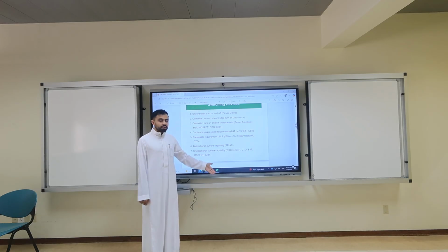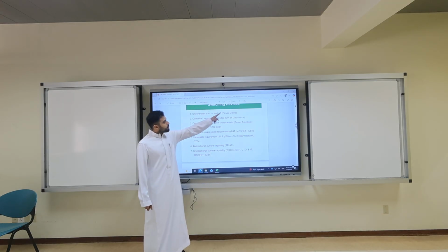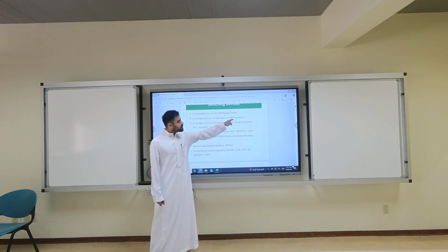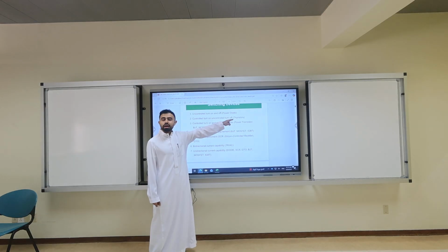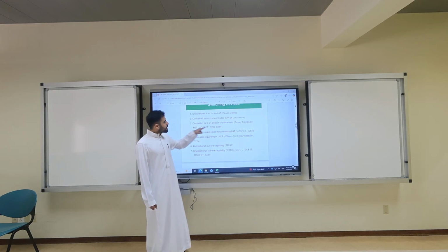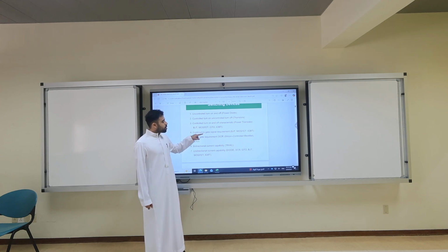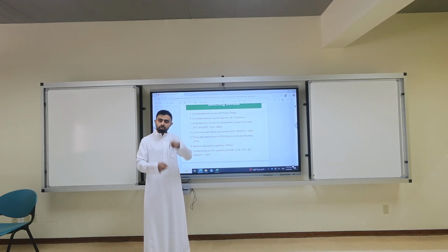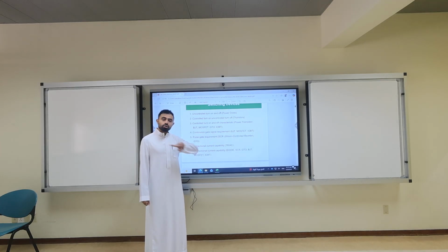Those are the devices that we use. We have a power diode. We will focus more on it. We have a thyristor. It's the diode, but you can control when it turns on, but not when it turns off. Or transistors on and off. Or a triac, which is two parallel diodes that you can control when they are on and off, but a triac conducts current in two directions. A diode in one direction, right? You remember that? Yes. A triac is in two directions.